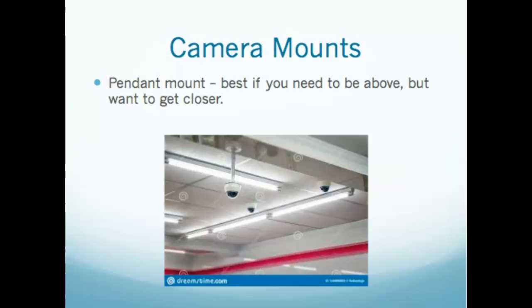Now, I would say in our warehouse that we are considering, you might be thinking that pendant mounts are good for the inside, and I would not disagree that, especially in that big bay area, they will give you a pretty good view. So think about the pendant mounts for inside. I would say in our warehouse, if you had 2 fisheye lens pendant mounts, you could cover that entire working bay area of that warehouse based on the size that's shown there, maybe 3, but I would say that you could argue that 2 could cover it because you're pretty high up.